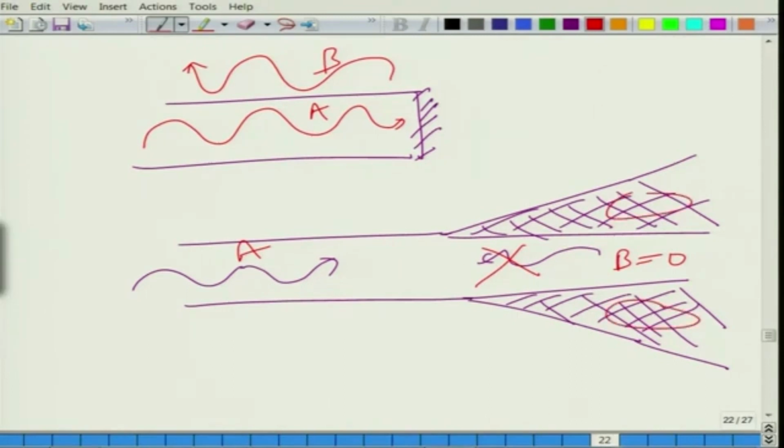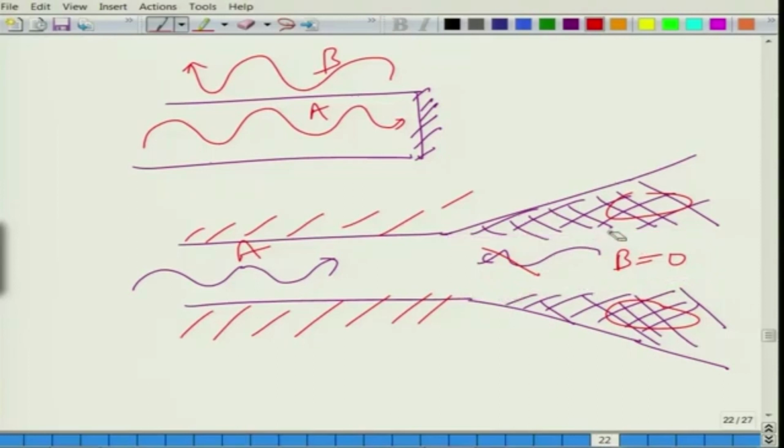Basically, they are nothing but mineral wool, glass wool or some absorbent material. All this while, this is a rigid cylindrical duct made of steel or brass or whatever it is, and here you have a conical termination, a conical annular area filled with rock wool, glass wool or some dissipative stuff, as the wave traverses through this path. And obviously I forgot to mention one thing here, they are not solid tubes, they are perforated.